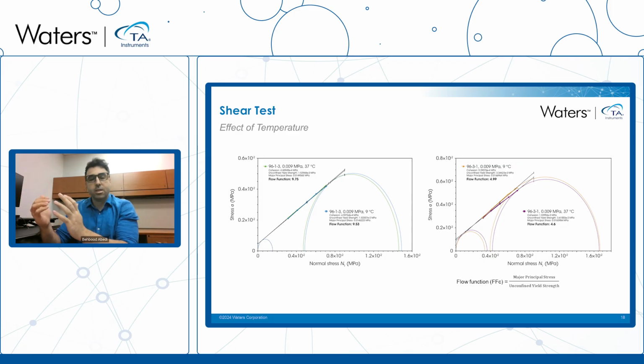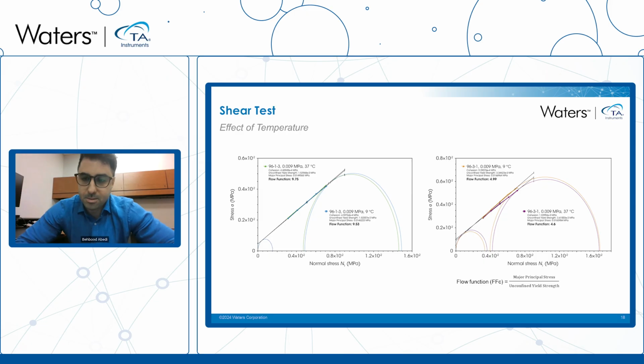So we suggest the preconditioning flow just up and down, at about 60 millimeters per second, to homogenize your powders.